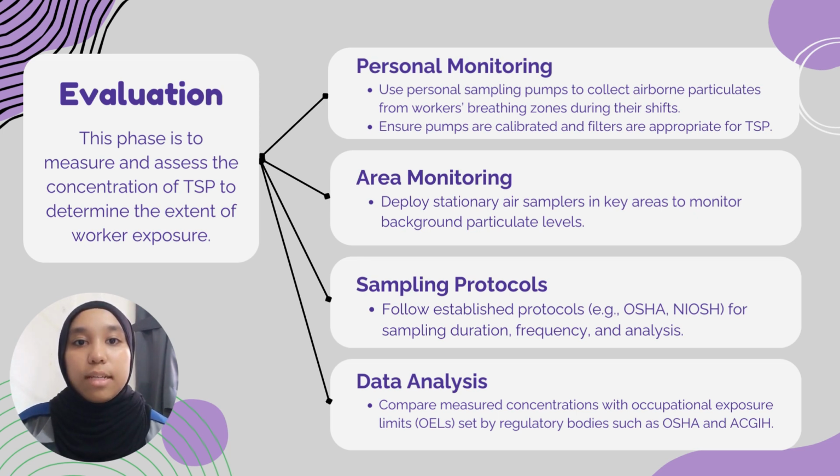So we need to follow established protocols, for example like OSHA and NIOSH, for sampling duration, frequency and analysis. The last one is data analysis. For data analysis, we need to compare measured concentrations with occupational exposure limits, which is OEL, set by regulatory bodies such as OSHA and ACGIH.